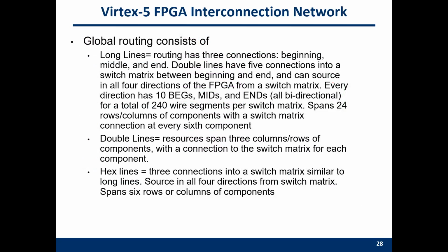It includes long lines, double lines, and hex lines. So different lines can support different connections. And the hex lines, of course, are the most expensive lines. They can support 3 connections into a switch matrix. Long lines are just the regular lines. They have a beginning, mid, and end.